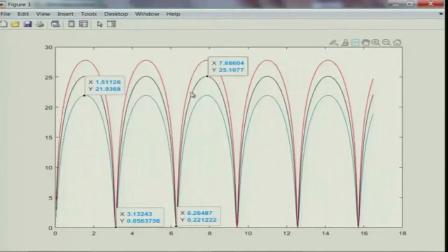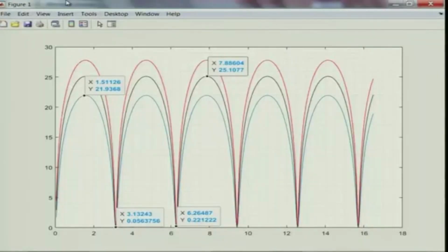So, we can obviously show a vertical line here to demarcate that beyond this frequency, do not consider the planar wave propagation very seriously, because it will eventually break down. Right now our world is only about planar wave propagation. So, let it be like this till we are confident in analyzing a large range of muffler elements like the ones we are discussing, extensions and resonators and all that, with the understanding that the cut-on frequency for the first higher order mode is the limit up to which these planar wave predictions can be considered seriously, beyond which we should not.